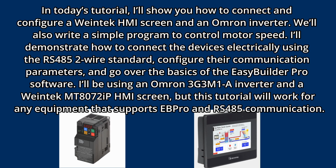In today's tutorial, I'll show you how to connect and configure a Weintek HMI screen and an Omron inverter. We'll also write a simple program to control motor speed. I'll demonstrate how to connect the devices electrically using the 485, configure their communication parameters, and go over the basics of the EBPro software. I'll be using an Omron inverter and a Weintek HMI screen.